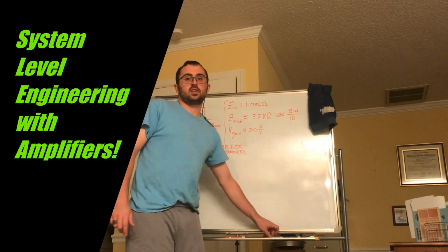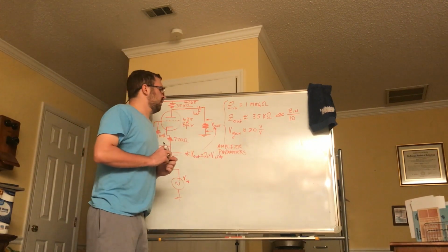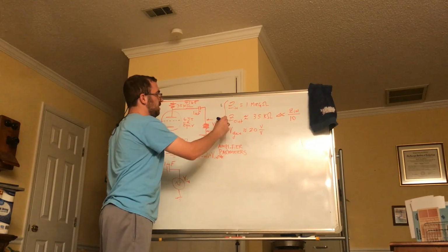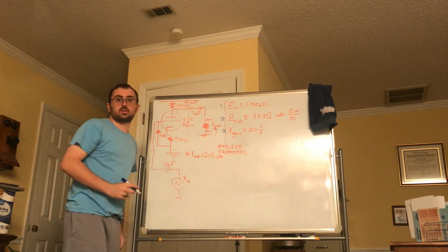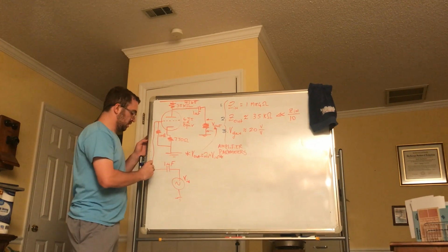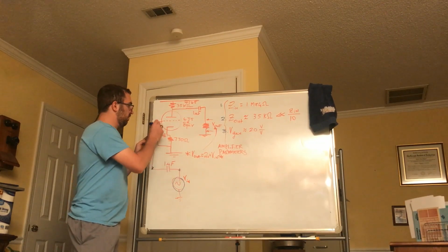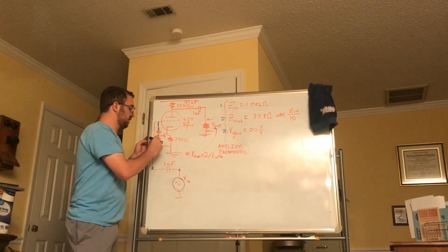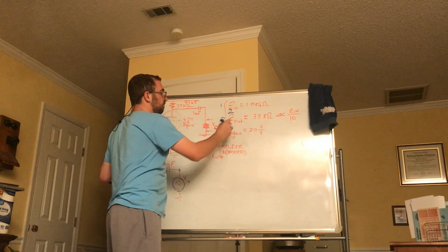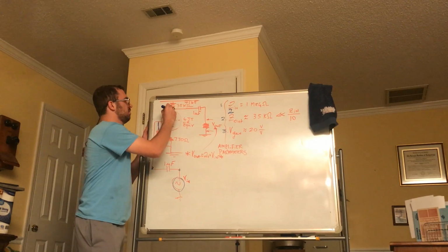And so in this video, I'm going to document system level amplifiers. So effectively, you have three main parameters: your input impedance, your output impedance, and your voltage gain. Of course, there are others, although they are related to these. Your input impedance is how low a resistance your input sees, and for tube amps it's really high, it's 1 mega ohm, and you can use higher. You want this guy, your input impedance, ideally to be infinite. Your output impedance is a different matter. It's on the output, which is the plate.